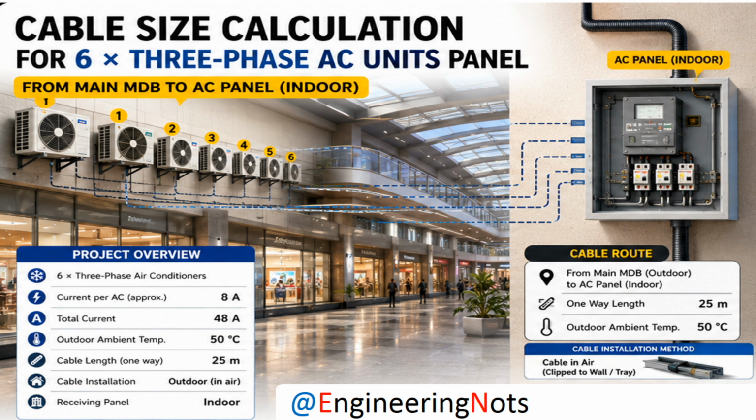They calculate 48 amps, look at the table, choose a cable, and forget that the cable is operating in a 50-degree environment. So the real question is not simply, can this cable carry 48 amps? The real question is, can this cable still safely carry 48 amps after applying all the required correction factors? That is the point where our cable selection becomes an engineering calculation, not just a quick look at a table.